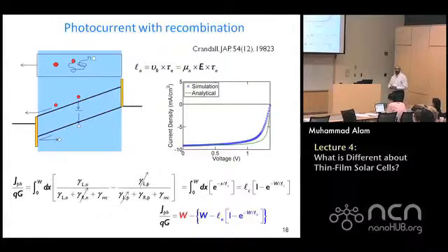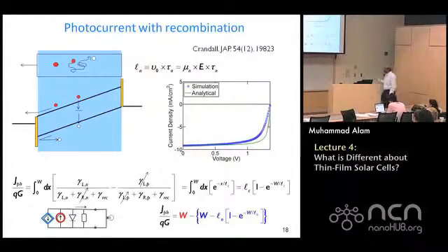Again, if you look at the original paper which derives this, that will be another 6 pages. But the essence of it is just this: you cannot get out without going through these recombination processes. So therefore you can rewrite it a little bit. QGW was my total generation, voltage independent, right?